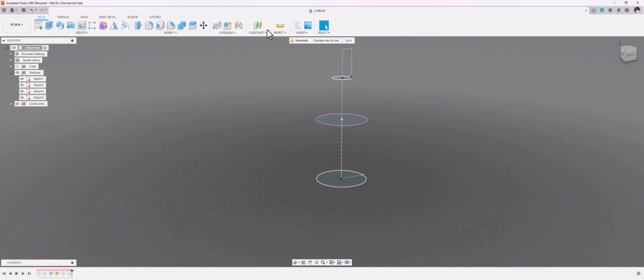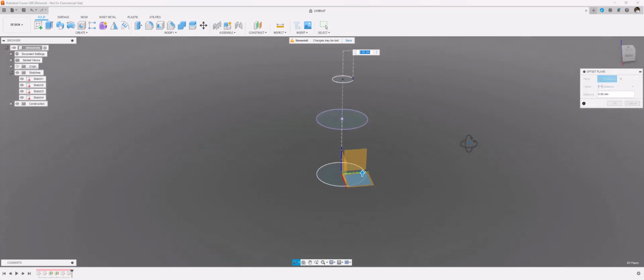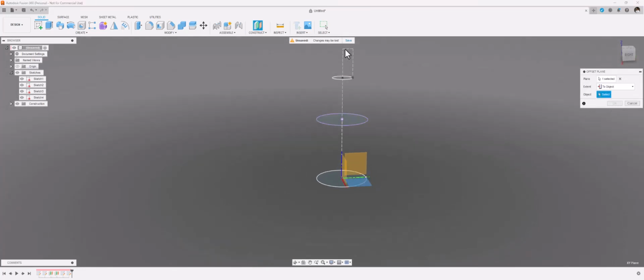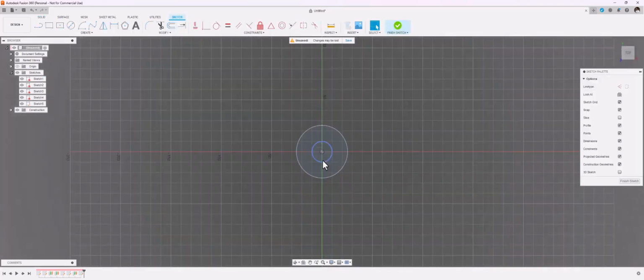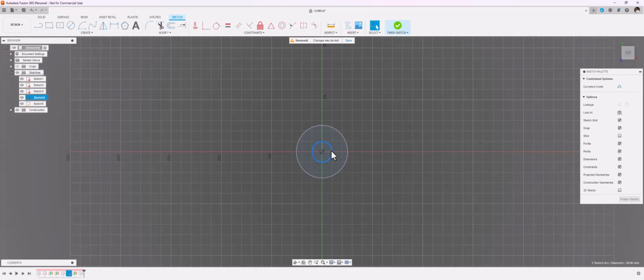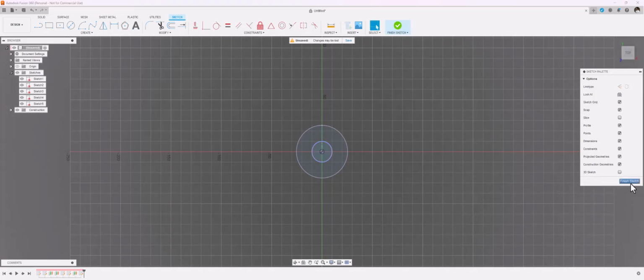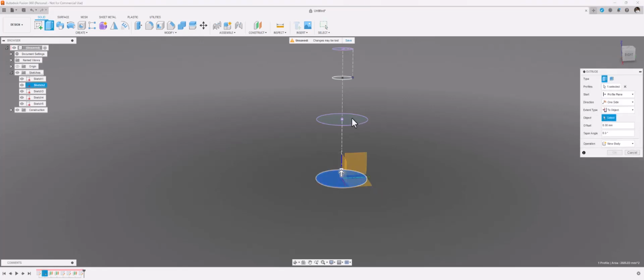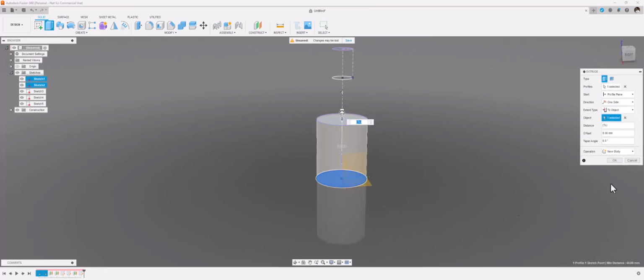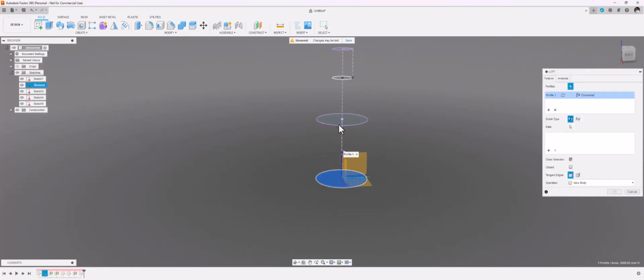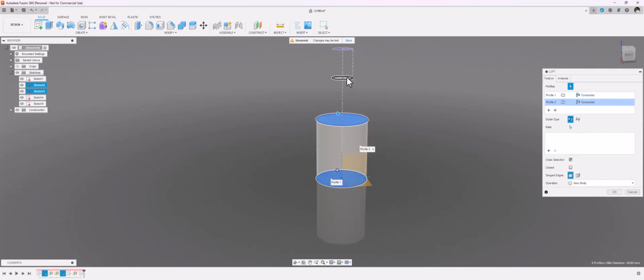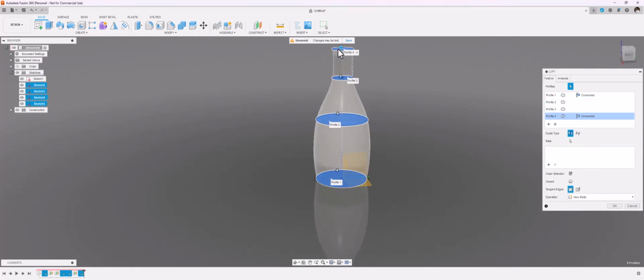And then I'm going to create one last offset plane from there to the top, to object here. And I'm basically going to clone that last image by projecting the neck again. So project. Okay, so we have these surfaces. And I could simply extrude that up to here and create that portion. What I'm going to do instead is use a more advanced feature called Loft, which is tell it to match that profile to there, and then to here, and then to here.